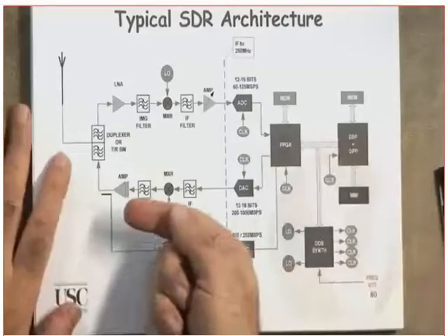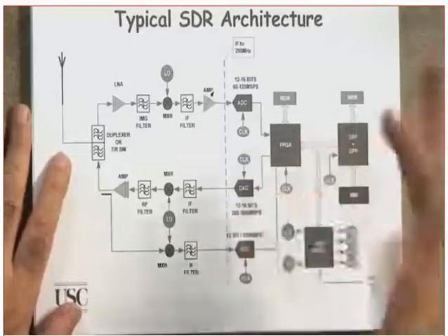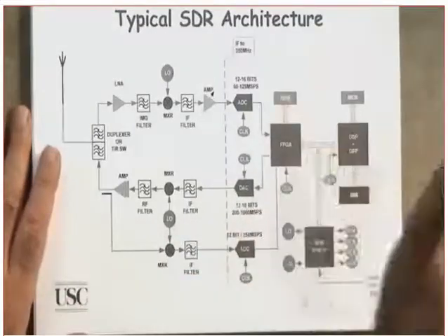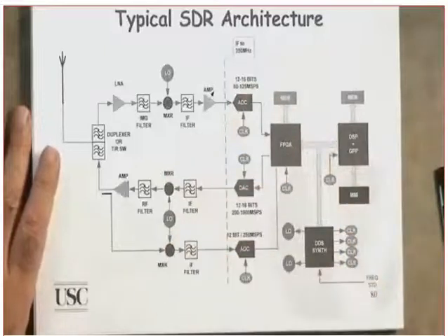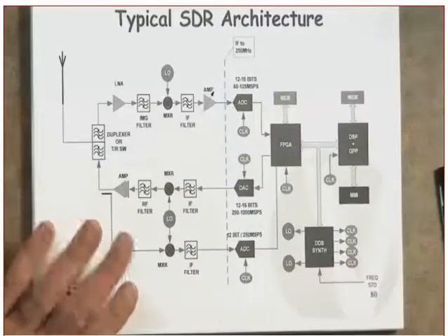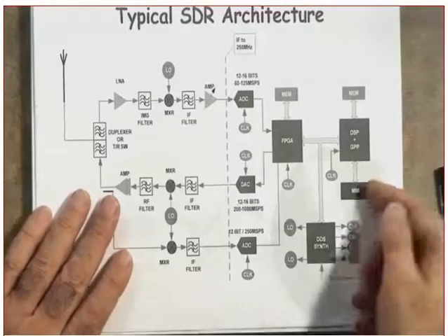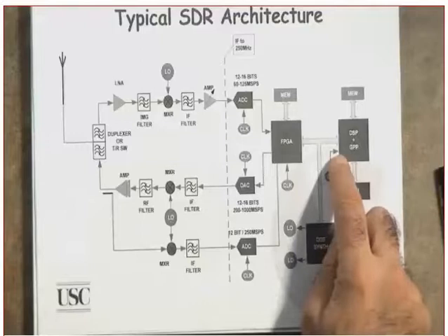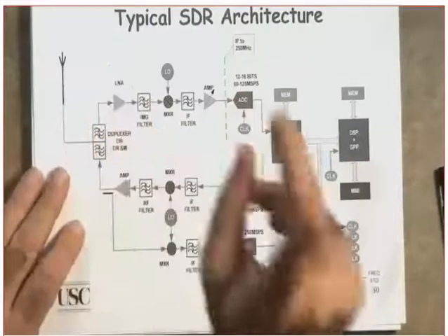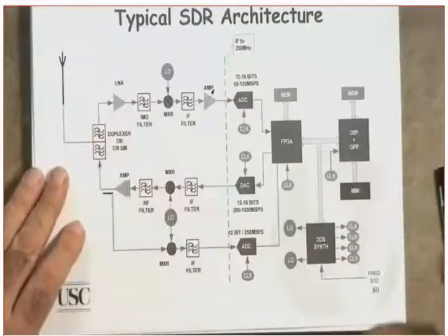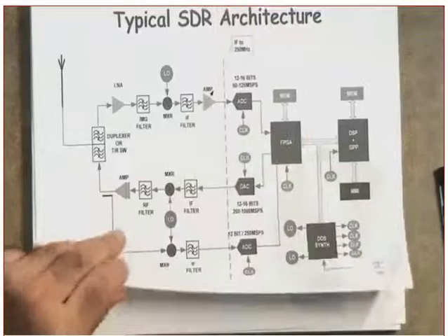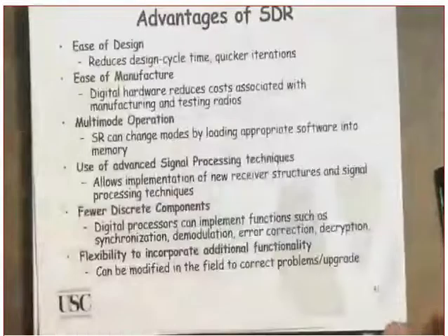On the other side, on the uplink, you are going to do expansion. And by expansion I mean you are going to interpolate those samples that you decimated. You are going to interpolate it again. Did you get my point or not? Which means on the uplink, when you are sampling at a lower rate, you need to add more samples by interpolating between one sample and another sample to create a third sample in between. Clear? Okay, good. This is an example of a software-defined radio.